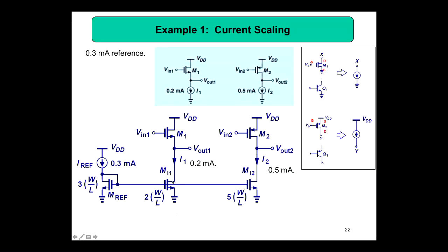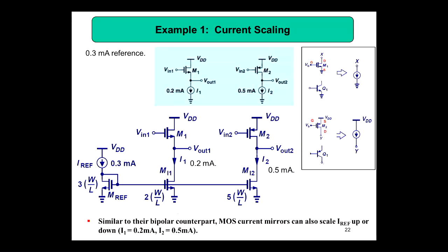So we got NMOS here, NMOS here, and the number is decided by how much current is required. Then you replace this I1 and I2 with M1 and M2. So this is biasing. Now we know how to create a current, how to design a current mirror, and how to use that current mirror for biasing a current source in the amplifier circuit.